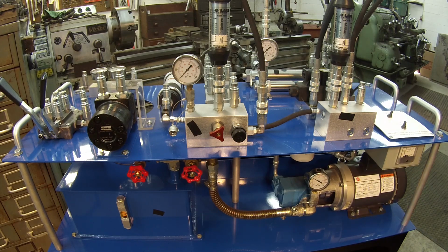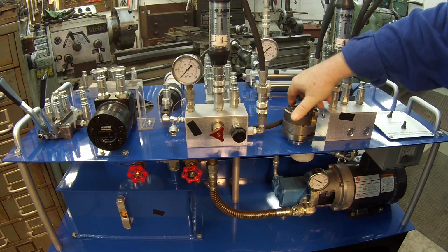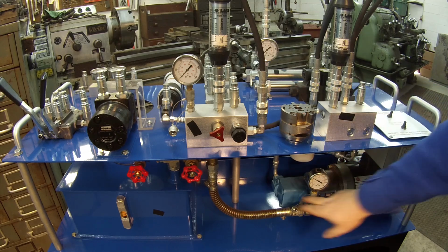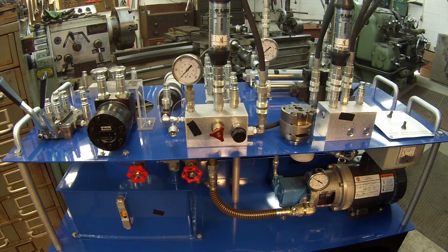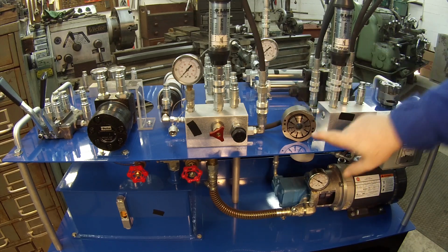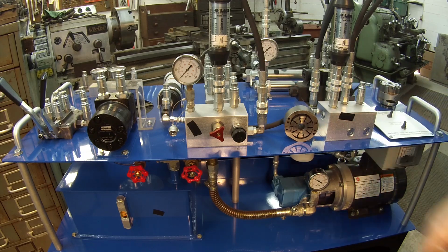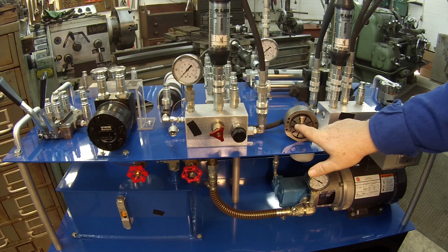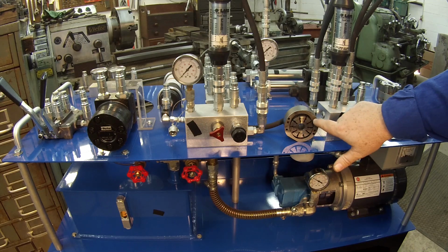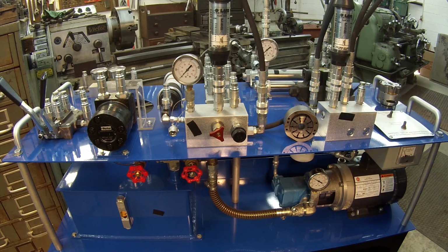So this is called a cartridge kit, and this has your vanes in it. Like inside this pump right here, you would have one of these cartridge kits. Okay? And inside this cartridge kit, this little ring right here, this is your ring and your rotor with your vanes in it right here. And so what happens is that thing spins around and your vanes contact this ring right here, and that's how you pump fluid. You've got an increasing and decreasing part of this ring right here, so that's how you pump your fluid in and out of this pump.